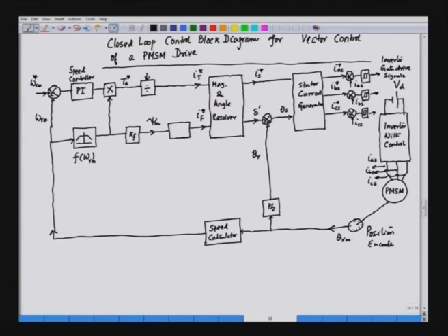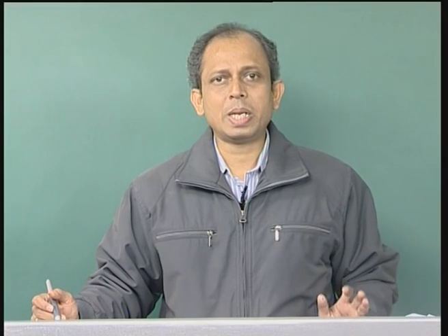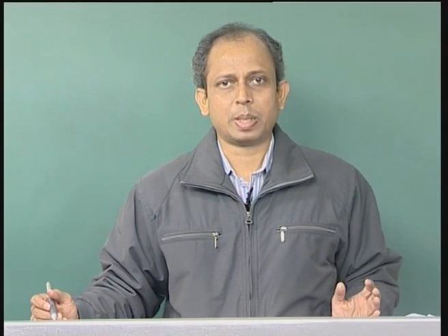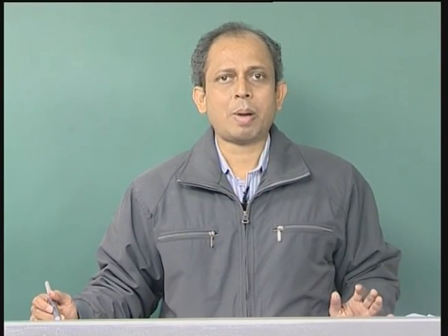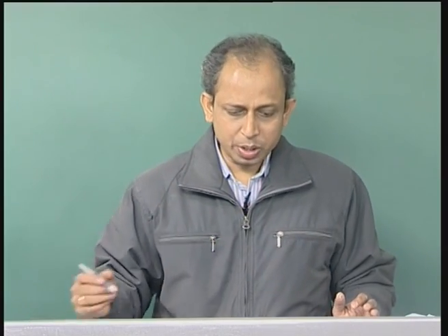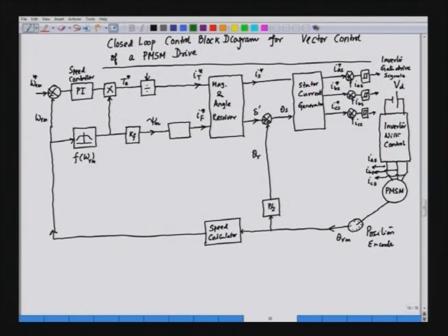An important aspect to understand here is that this block diagram can control the speed below the base speed and above the base speed. Below the base speed, the magnetizing flux is constant. So, if we see this function block, this is the functional block that we have added here. This functional block has a typical characteristic. Up to the base speed, the flux remains constant. So, this basically gives us psi m versus omega r m. The x axis is omega r m and the y axis is psi m.